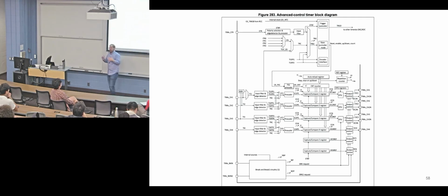So if you had, say, 6 LEDs that all needed to be a different brightness, or you want to do RGB LEDs, in which you need 3 pulse width modulated waves for each color, and then they get blended in the LED, then you only need one timer to control all of those different things, and those are just pulses that go out of your chip.